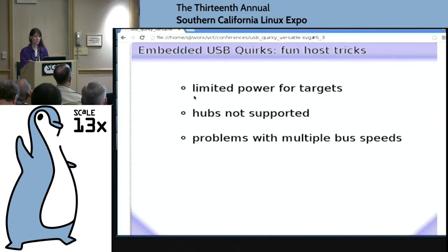This is another one that I found that is major, major pain. On a desktop, you would probably throw it out if you found that your mouse plugging in was interfering with your writing to your USB storage. But like, what were these stupid manufacturers thinking? But again, the very cut-down USB chips can have a problem when you're doing the old USB 1 and the USB 2 devices at the same time. So if you plan to do it, just beware. That's the next slide.